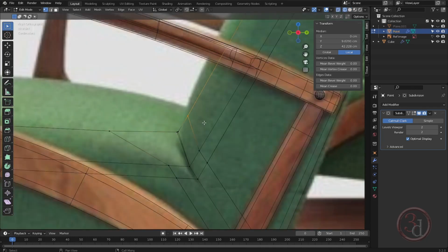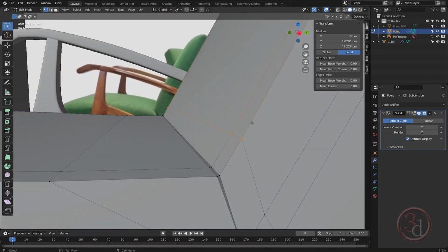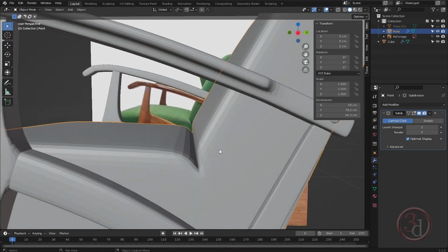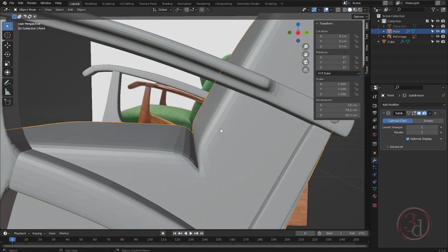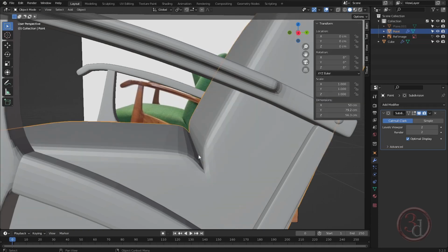Come here, select the points in the wireframe mode. And if I want to align to this axis while I move, what I can do is press GG, so it will stick to this angle. And now see the result. It's getting better. GG again, go further up. Now if I close in the points more,